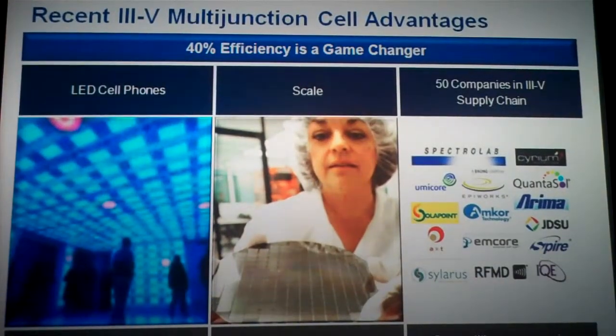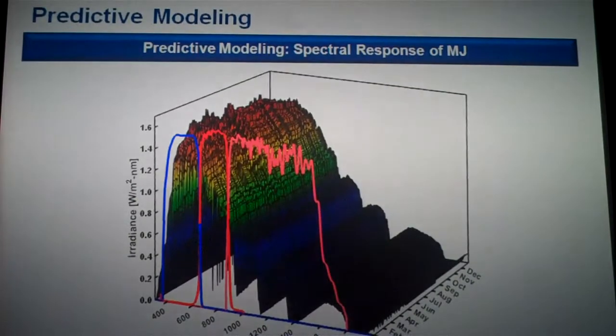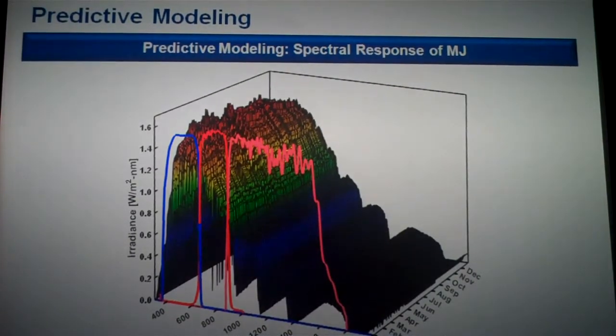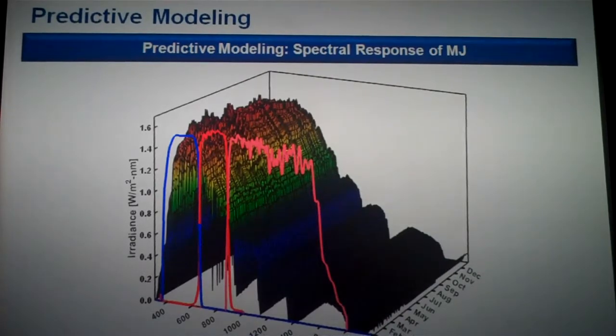This is showing more of the cell used in this one. We call it multi-junction solar cells, which Dr. Kevorkian can touch upon. And here I'm showing the spectrum of the sun. As he said, most of the devices made today, whether thin film, copper indium selenide, telluride, crystalline silicon, or non-crystalline silicon, they all only see what we see. The rest of it is filtered out. So it doesn't absorb the spectrum beyond approximately what we see. Like Dr. Kevorkian said, there's a lot of energy all around it, and so how do you harness that?